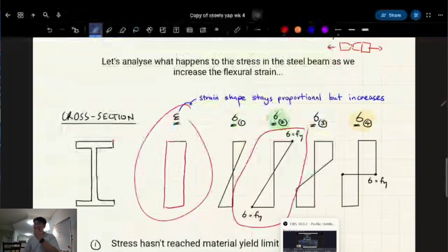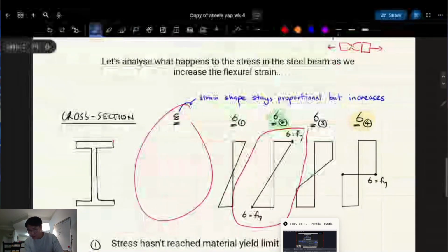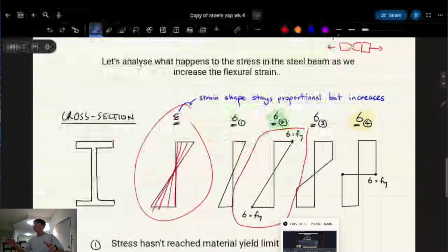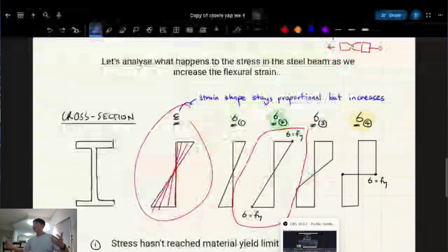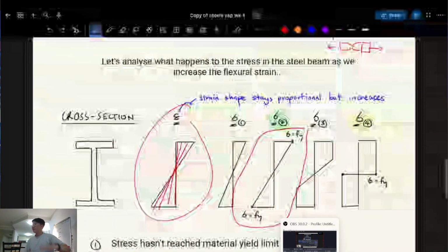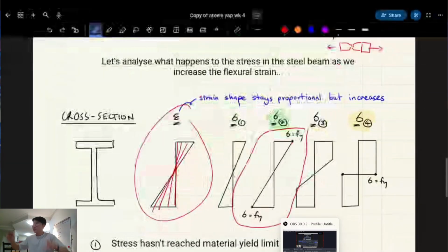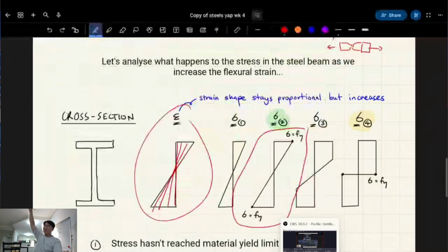But then if I talk about it in terms of that, it means I'm applying an uneven amount of strain. So you're bending it. Exactly, I'm bending it, because the top's in compression and the bottom's in tension. In normal bending, the very top and bottom fibers will yield at the same time if it's symmetrical. But it's a different type of yield, because the top will yield in a compressive way, and the bottom will yield in a tensile way. Does that make sense? Yes.